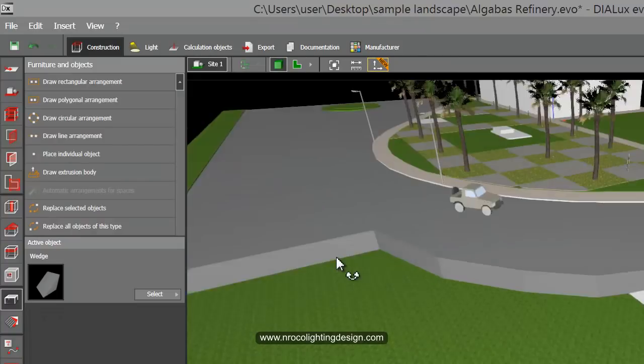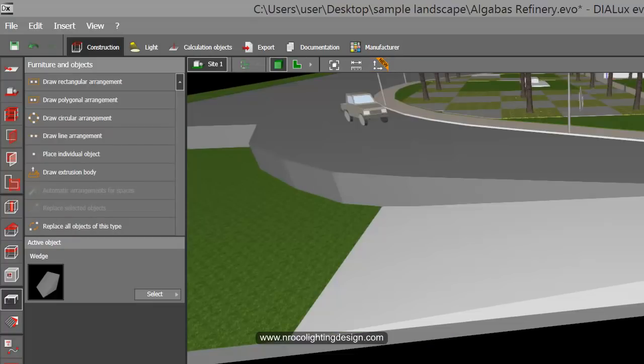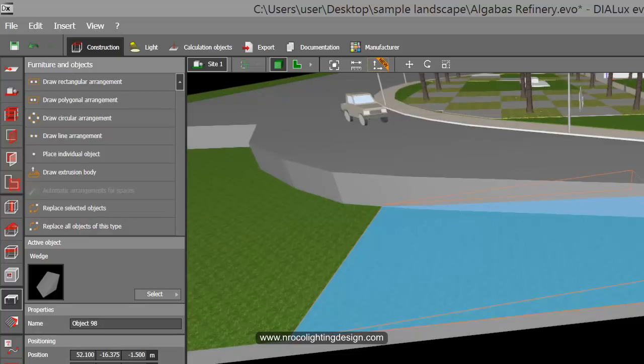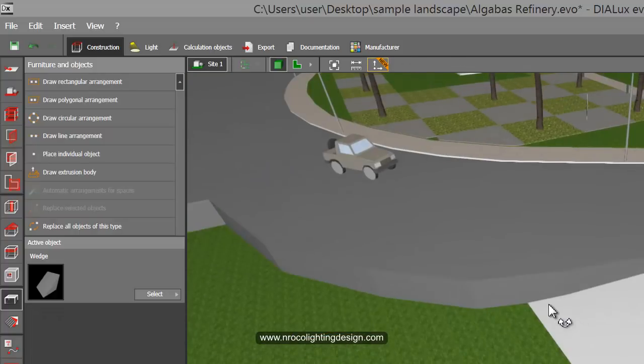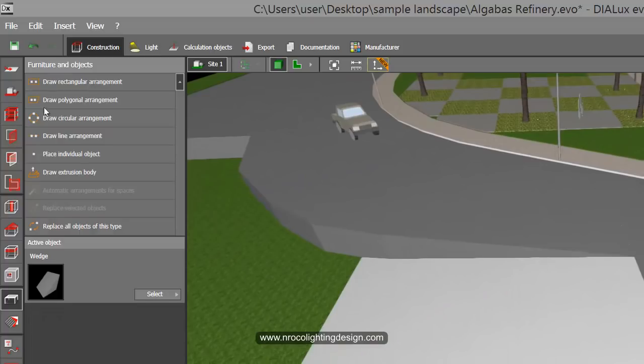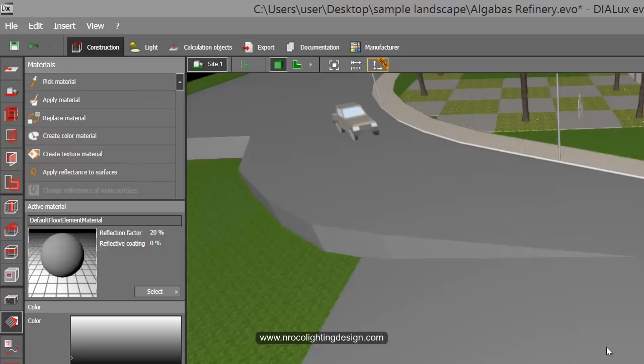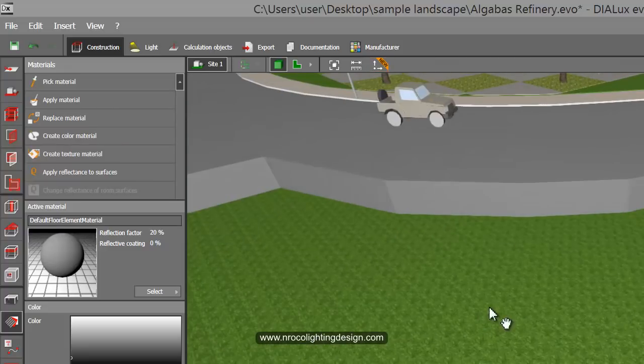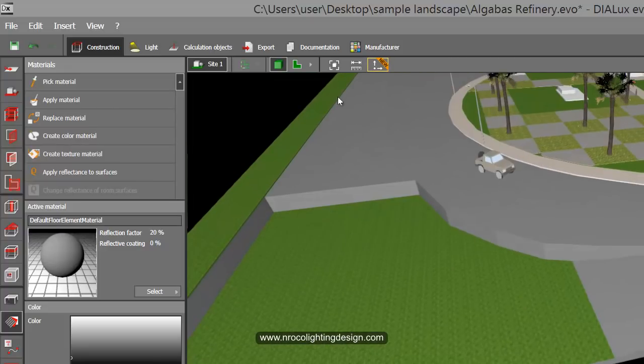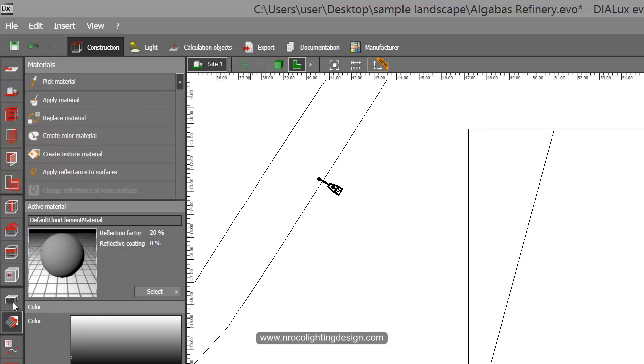Okay, so this is your floor element, and because the default height of your ramp is only 1 meter, you can adjust it into 1.5. All right, now there you go. And you will either choose the same color like this one, or a grass if you like. Now if you like stairs, then you can do it by using the object, or again a floor element.